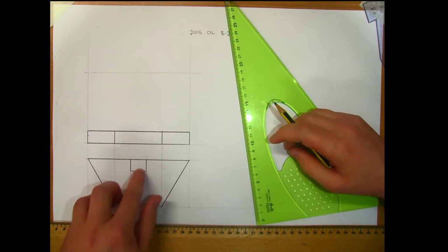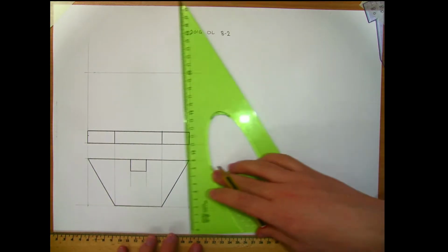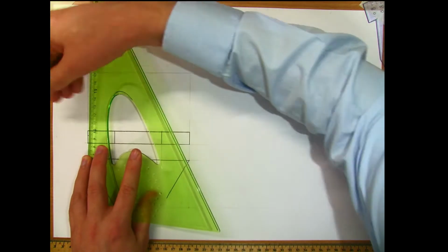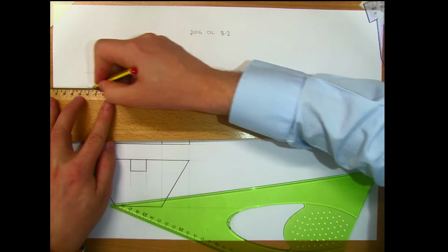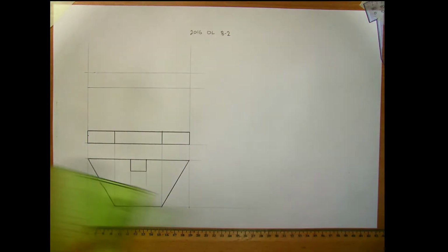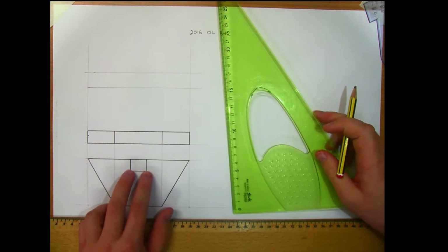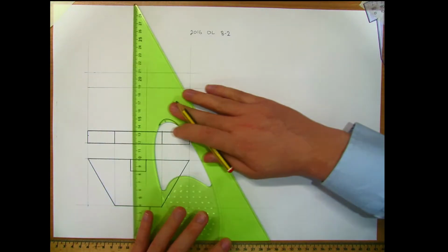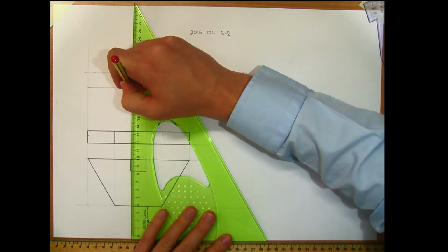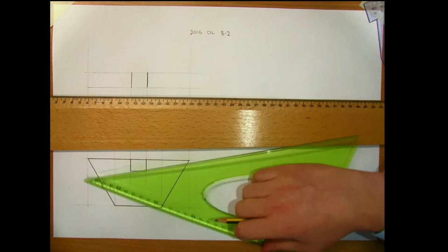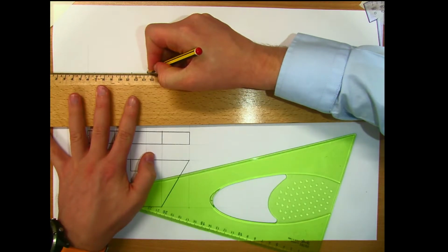What I'm going to do next is this part of the hood, which is going to be up here. It's up high, and we're told that it is 55 millimeters above the top part. So 55 millimeters is going to be up here. So it sits in that area there and has the height of 20, which we already have marked because that fits into the box that we drew earlier. Again, our widths are going to stay the same, the lengths across here, as they are in plan. So I'm going to take this line, project this up into the elevation, and this one. And this will give us the width of the narrow part of the hood, the funnel. Here and here.